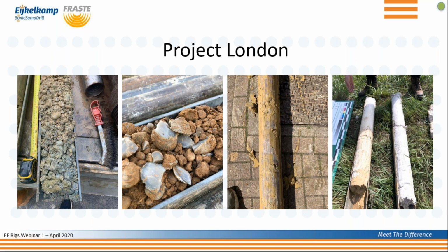Okay. And then the final question on London drilling experience, because you've been working there the most. How do you cope with geotechnical class samples like the UT100 or the U100 with the Sonic? Not an issue at all. We can lower the UT down and drive it in with a weight, not a problem. Exactly the same as a cable percussive. We can Sonic it into the UT100, not a problem.